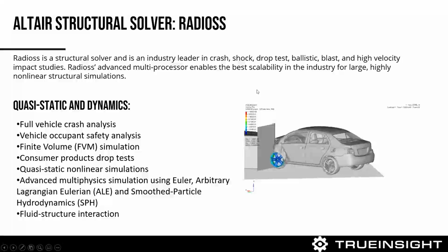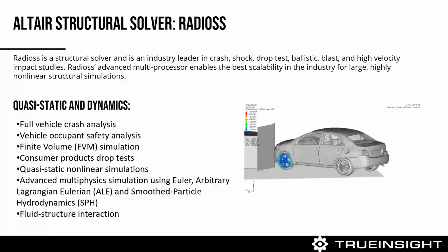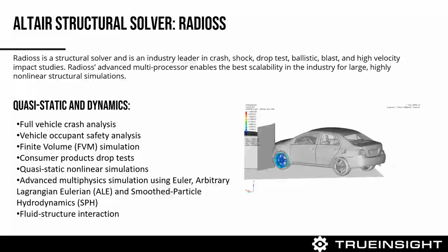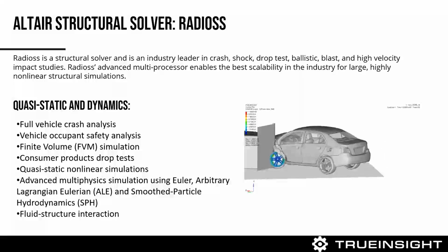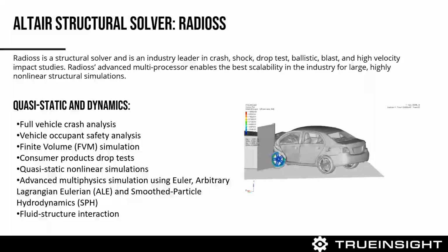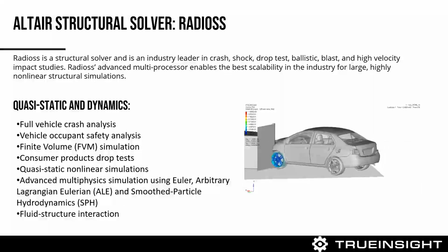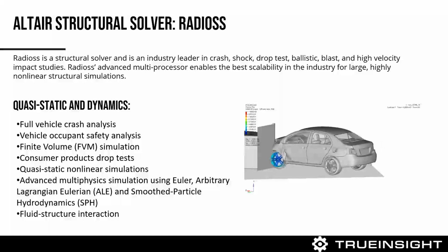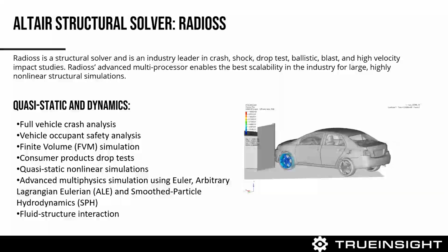And let's now talk about our other solver, which is RADIOSS. Similar to OPTISTRUCT, RADIOSS has traditionally been known as our explicit solver. Note there are some implicit capabilities. What I typically recommend customers use OPTISTRUCT for is traditional implicit, and then high energy events is where you use RADIOSS.